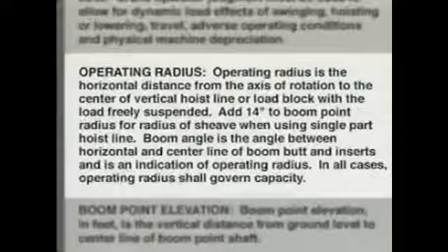Different booms can be used on a crane, and different jib combinations can be used with each boom. The load charts that come with a crane include jib lifting capacities charts. In order for a jib capacity chart to be used, all the requirements listed on it, as well as those on the main boom capacity charts, must be met.